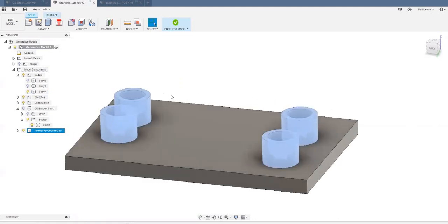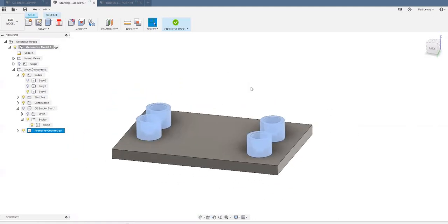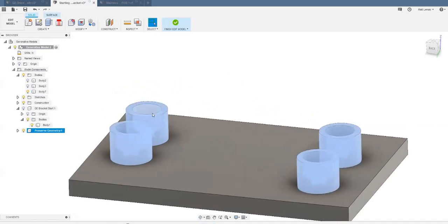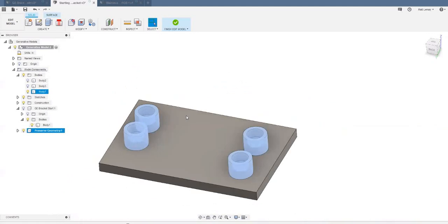So the next thing that we need to factor in is that we also need to create obstacle geometries for where our fasteners are actually going to be located. So within each one of these pins, we know that we're attaching a fastener to it. And we also need to know that we have assembly clearance to that later on.